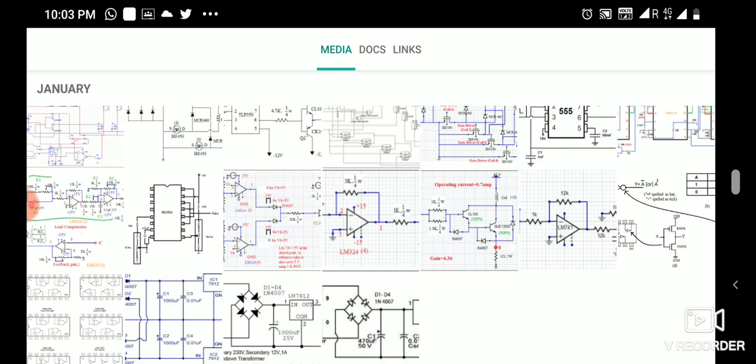Suppose we use fixed resistances in the lead compensator, then we have no provision to change the resistance. We would have to remove the soldering, which is very risky. So it is better to use some pots if fine tuning is required at the last step. Then it completes. Next day also we will discuss circuit design and fabrication. Okay, thank you.